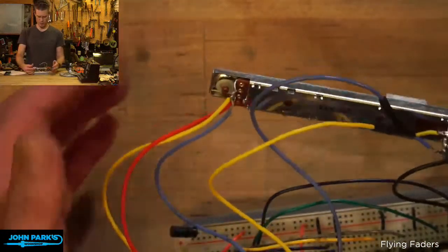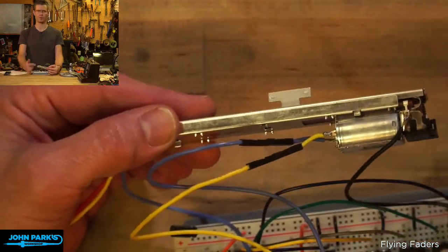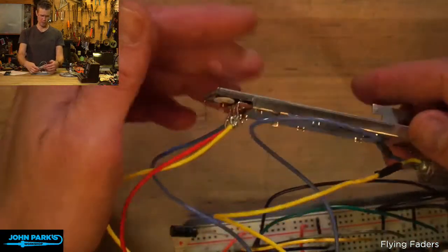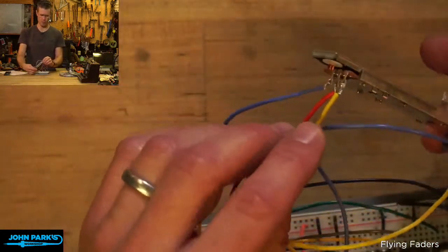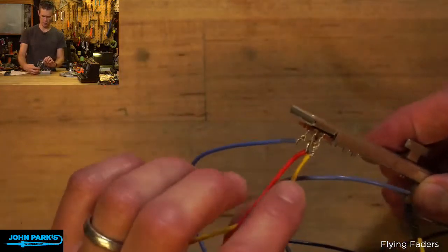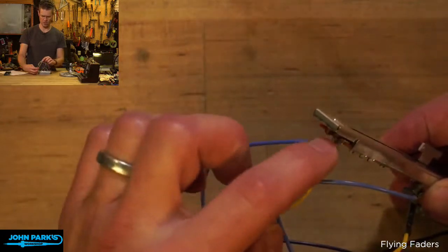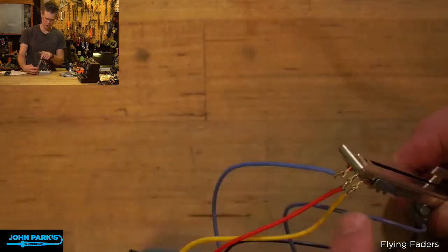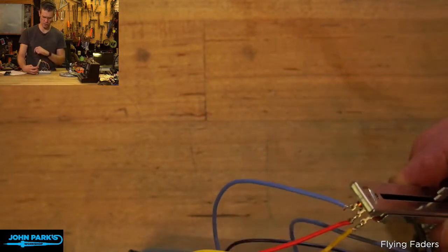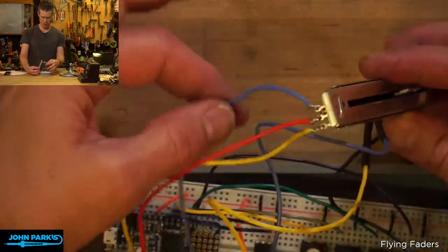The other connections on here we have, so just ground down at one end, and this is pretty typical for faders. You'll have the ground pin down on one end by itself, and then usually the wiper and the voltage pin, positive voltage pin, will be at the other end. Which are what this yellow for wiper and red for voltage. And again, these are just some wires I soldered on there. I also need to put a little heat shrink so I don't get any whiskers of wire touching each other. And then this last one, this third connection here, that's the touch, capacitive touch.